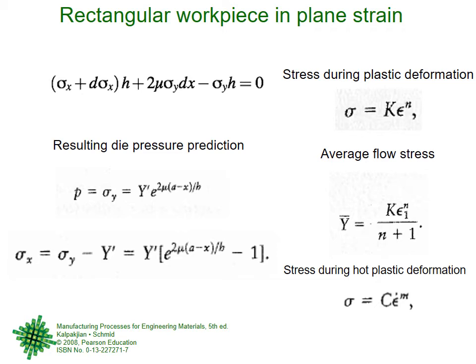Now if you go further, you see this is the stress. Actually this is the value which they are calling Y in this book, any plastic stress anywhere is called Y. Now in forging, for example, you start pressing and you keep on pressing until that material is completely pressed into the die shape, and you apply that pressure for some more time so that it is permanently in that shape.